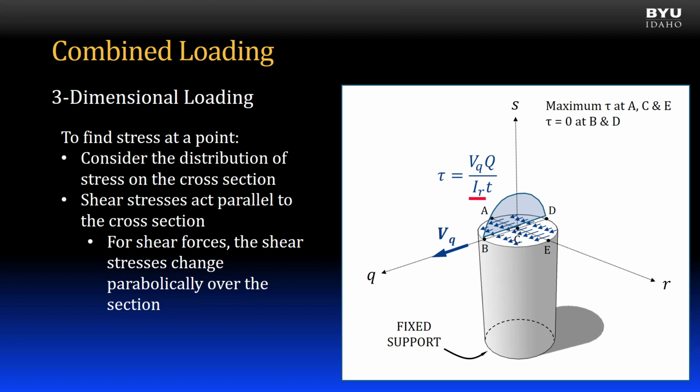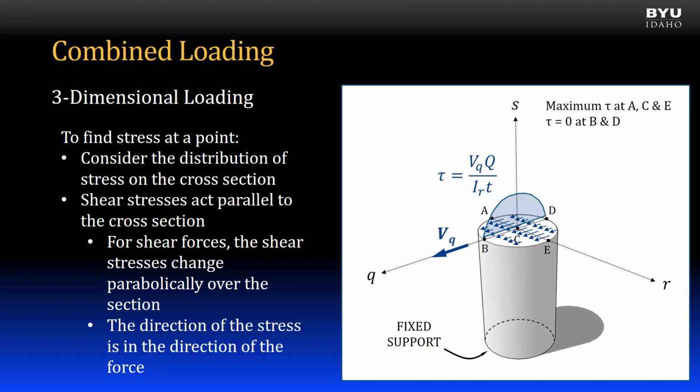Note that the moment of inertia is about the axis perpendicular to the shear force direction, and the dimension t is measured perpendicular to the shear force direction. The direction of the stresses are in the direction of the force.